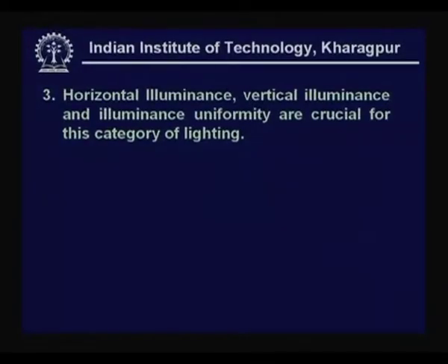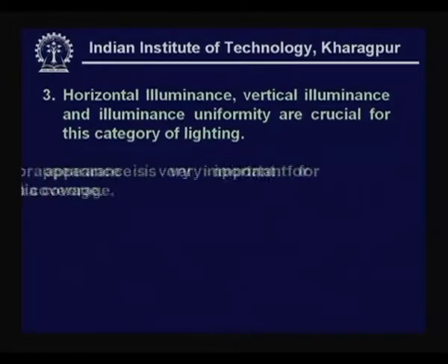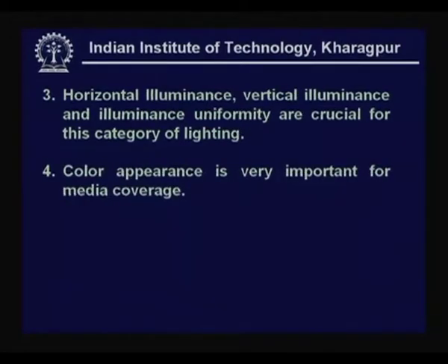was grouped under B. Horizontal illuminance, vertical illuminance and the illuminance uniformity are important for this kind of lighting, and in fact we have had a look at various recommended levels according to CIE for the sports lighting from all these angles.